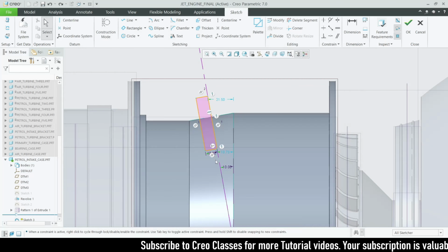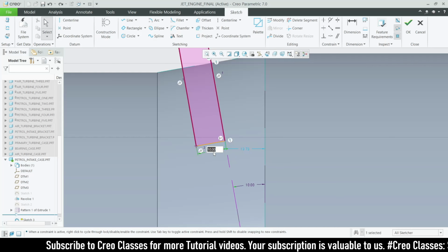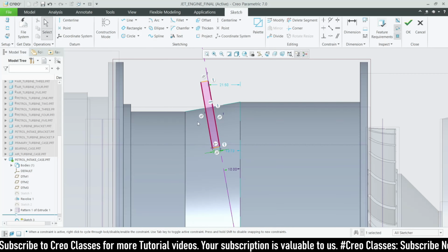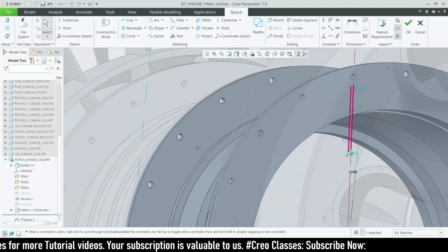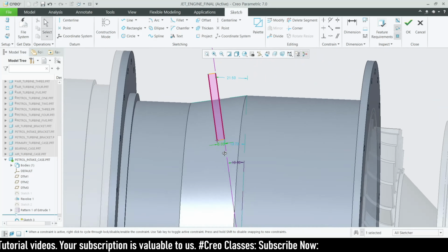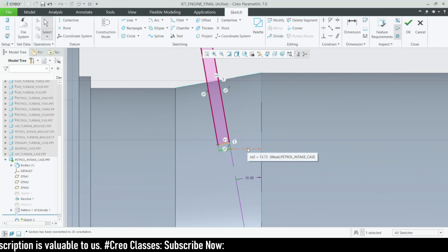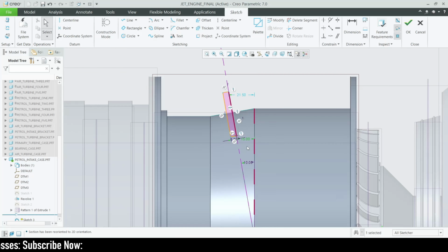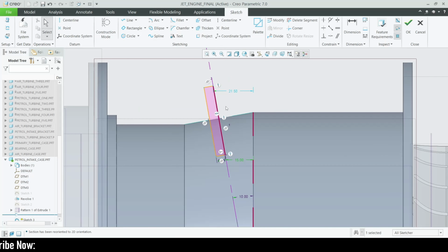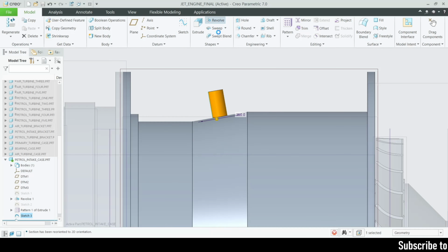Okay, right, we are just going to revolve this. So here, this entire value is 10, but I need a value of 5 because we are going to revolve this feature. And let's check whether, yeah. So for this bottom, okay, an increase, because I don't want this. Okay, so it is 15. So now let's click on OK and let's go for the revolve.